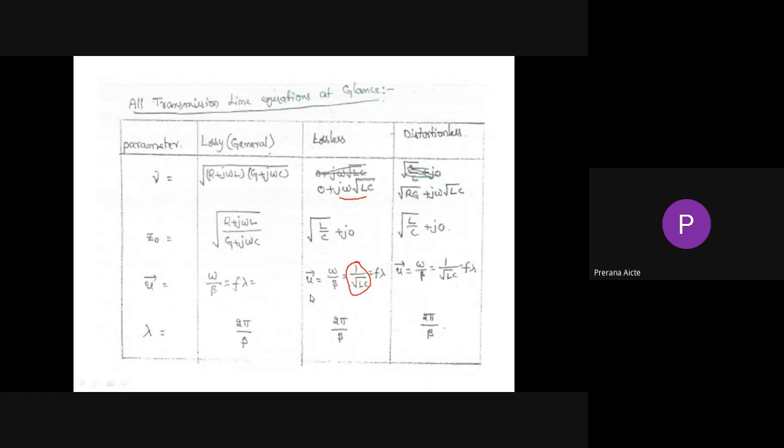Resistors and inductors are connected in series along the line, and conductance and capacitance are connected in parallel. R, L, C, G are called the primary parameters of a transmission line. Using these, we derive other parameters, which we call the secondary parameters.